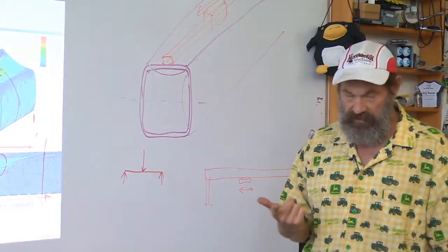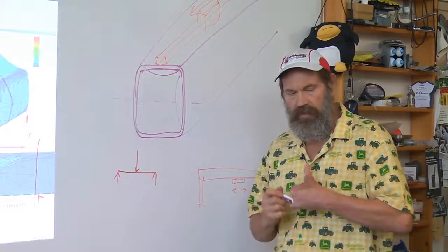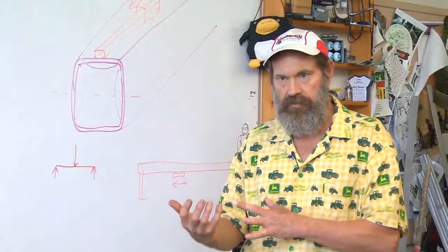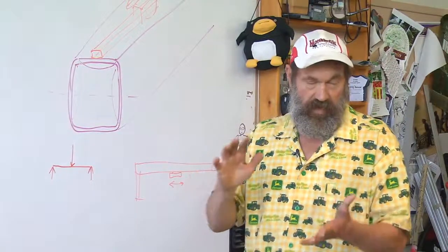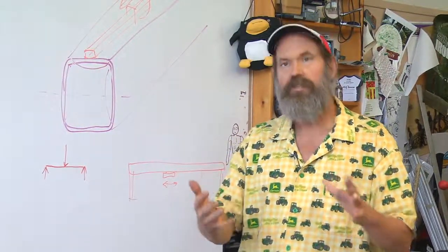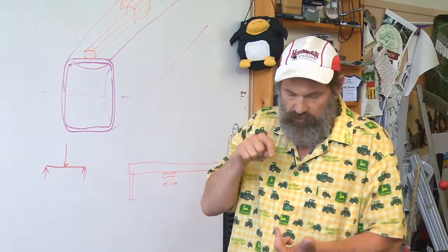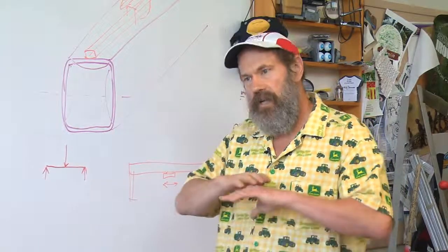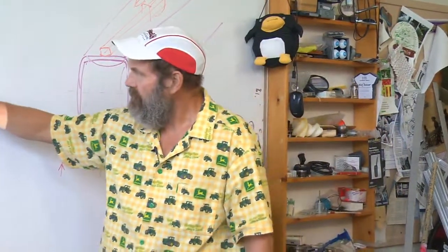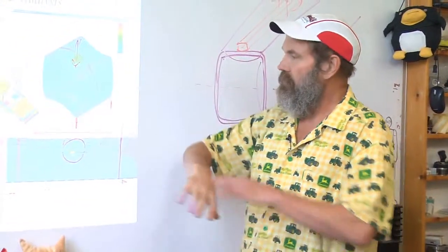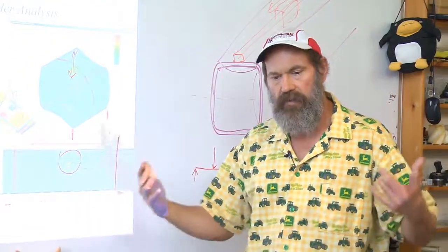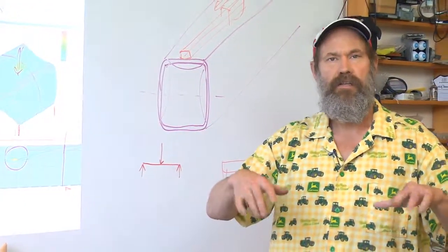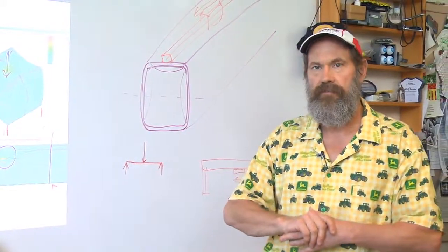So these are very, very powerful tools for your first order analysis, both for strength and for stiffness estimation, of taking the appropriate dimension slices out of a complex structure, governed by St. Venant's principle, is how you proportion those slices when you pull them out. To do your local quick estimate, closed form of the strength or the stiffness, it allows you then to size things in terms of your wall thicknesses, your dimensions, complete the rest of the design of the structure, and then when you have the rest of the design structure, then you can do the finite element analysis on the complete machine to check the strength and stiffness of it.